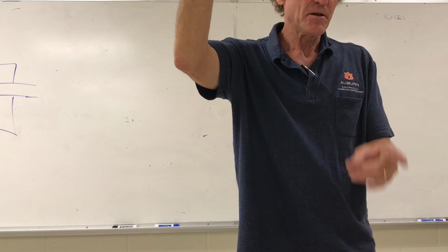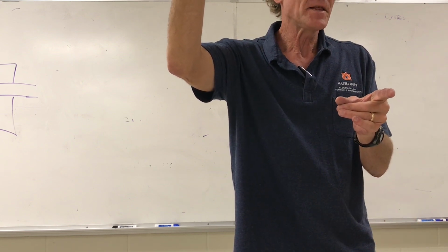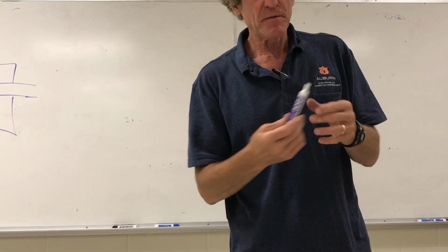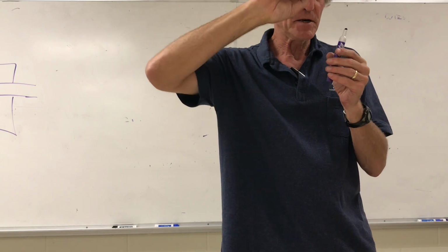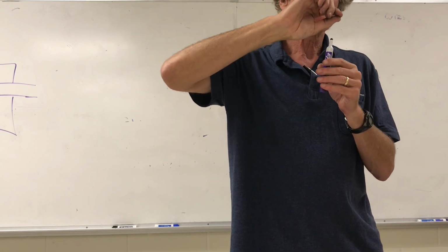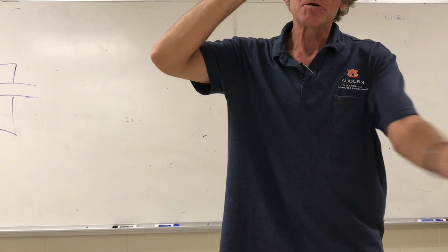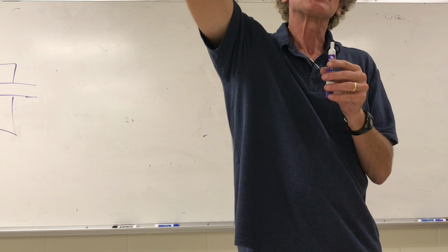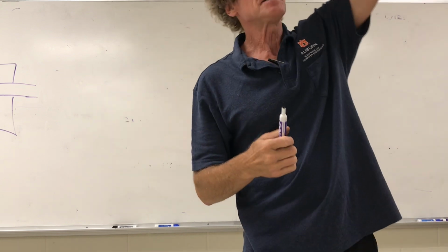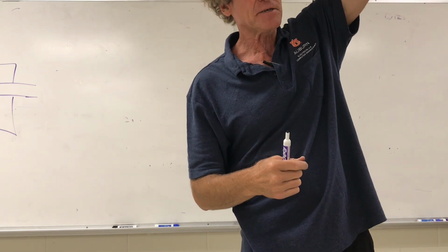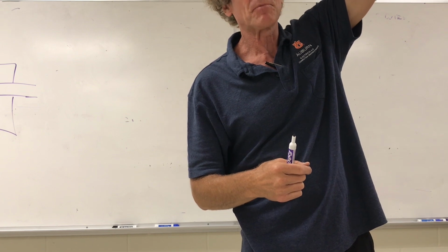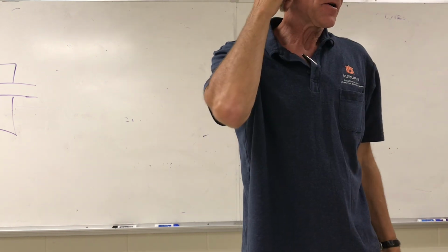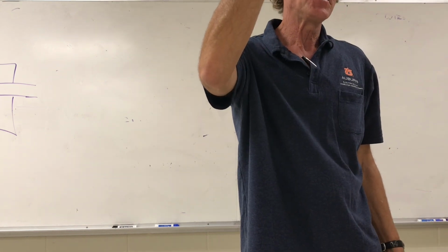All of a sudden, you get a larger and larger value of electric field. When that electric field goes over a certain threshold, which is 3 megavolts per meter, and it's very easily done if you have sharp points because you get field enhancement around there, then you get something called ionization. And if there's enough charge under there to support a current, you will just see this thing shoot up. It's called a stepped leader, a little filament, until it gets to the cloud negative center, and then all of a sudden all heck breaks loose because that's an ionized channel, and now there's a direct short for the other current, and it will heat up and expand, and you'll get a huge amount of current.